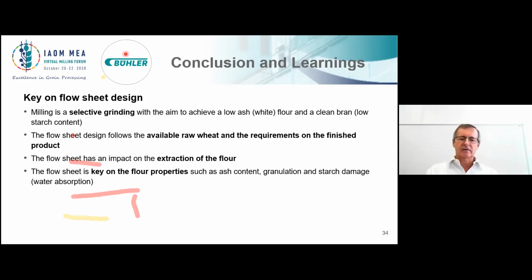This is a loss in extraction. So we need to have the purifier sieves more open than the plant sifter sieves. The biggest sieve is at the top end, and then we gradually close down. First of all, design, or let's say calculate, first the biggest sieve on the purifier and go in steps down.